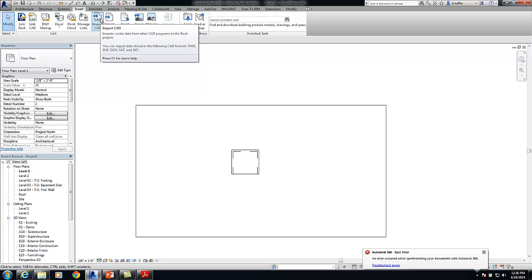and import a CAD file. So I will take a brand new family, maybe it's just a detail family that I'm creating, or a repeating detail. I'll import the CAD line work and I'll maintain the colors. I won't convert it to black and white. I like to see it as colored information so I know, hey, this isn't Revit. We're going to trace it, or we're going to use the pick tool to recreate it. From there, I will remove the CAD data and save it out as a family.